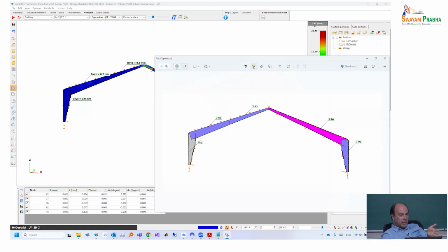And I calculated, based on this criteria, 16 buckling modes. So none of the 16 was significant enough for this column. Now I can have two choices. I can start to increase my limit to calculate more, accept more, and try to see when I get to that one which will be fine.